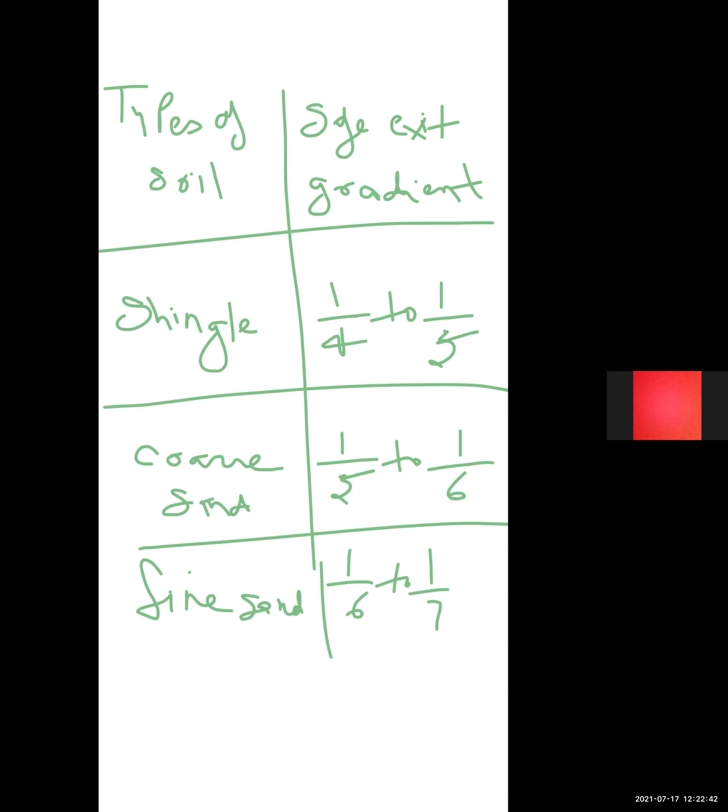So it can be concluded that safety against piping cannot be obtained merely by providing sufficient floor length, as stated by Bligh, but can be obtained by keeping the exit gradient well below the critical value. So the exit gradient may not be safe even if the average hydraulic gradient of Bligh is L by C.